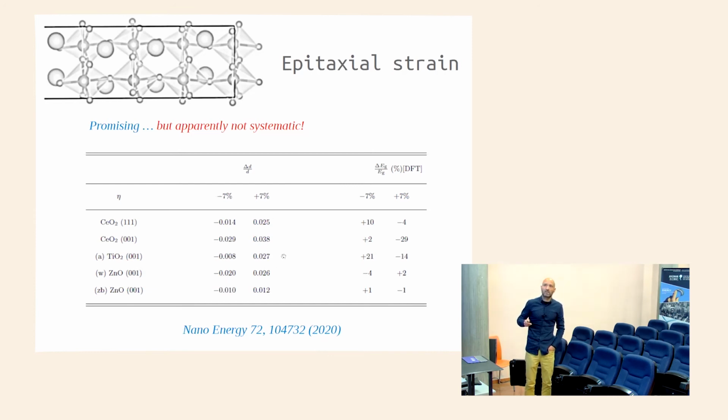However, this is, in other words, the structural properties of how you change the distances between the atoms. Of course, it will depend on the mechanical properties of the material, the elastic properties, but most of the time you will end up having an increase of the distances on the tensile side and a decrease of the interatomic distances of relevance on the compressive side. However, that's not reflected in how the energy bandgaps change, right?